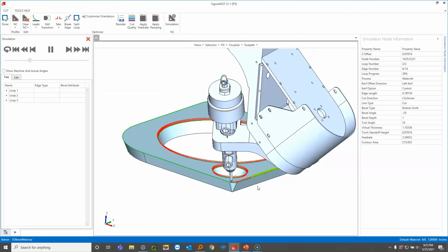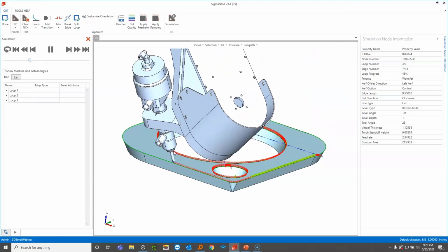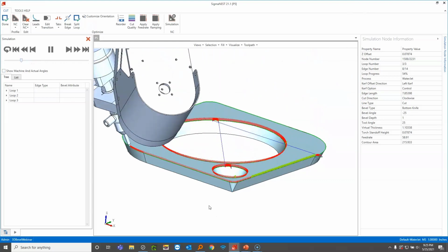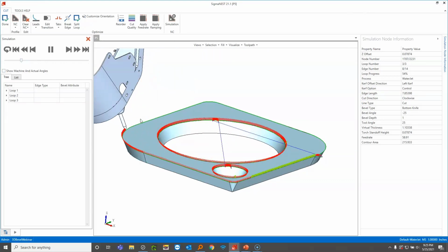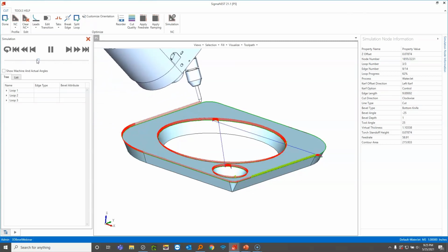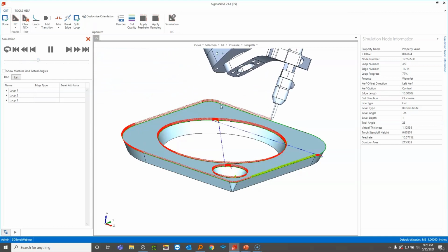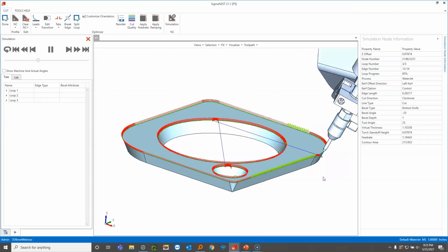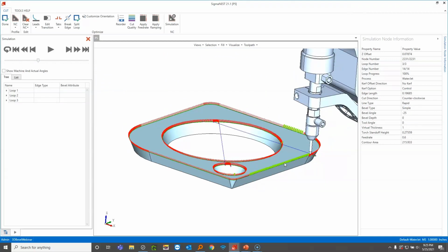Okay, so it's coming here. And notice when it gets to that corner, you see it dropped all the way to 2 when it got there for that small radius. And now this is a large one, so it's not going to care. And yeah, that's pretty much what it's doing, is it's looking at that rule that we set up, and it's working with the tech table to kind of ramp down to what it's set there using those rules.